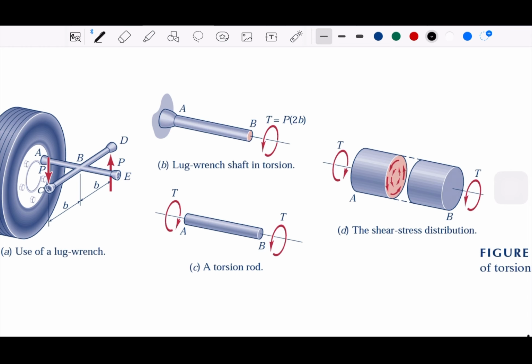When we twist this, aside from the forces that are going to be distributed inside the rod, if we see how the blue line here is going to be twisted, right? The twisted means, if you remember what we have learned before, the shear strain, it has some certain angles, right? And that angle also will be incorporated in this torsion.